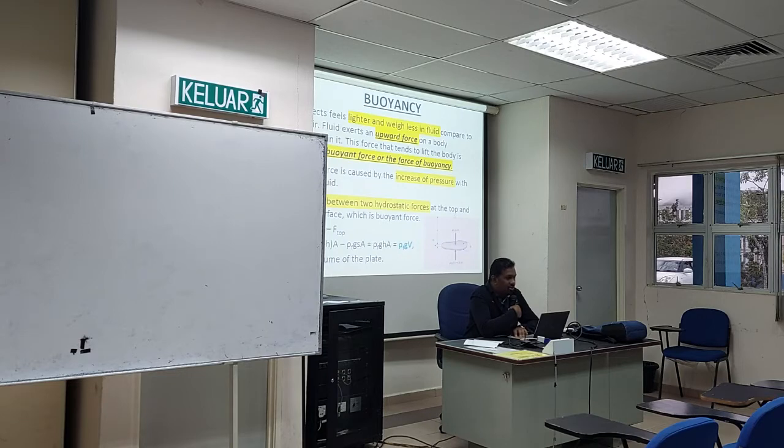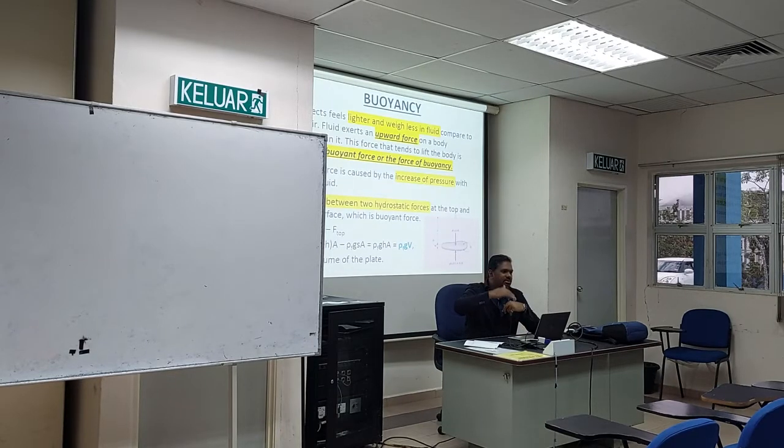Buoyancy is an upward force inside the water. In layman's terms, whatever makes you float inside the water is what we call the buoyancy effect. You can see here, buoyant force is caused by the increased pressure with depth in a fluid. What is causing the buoyancy force? We know there's a pressure difference between depths. In water, the deeper you go, the more pressure. Because of the pressure difference between one height and another height inside the water, we have this buoyancy effect.